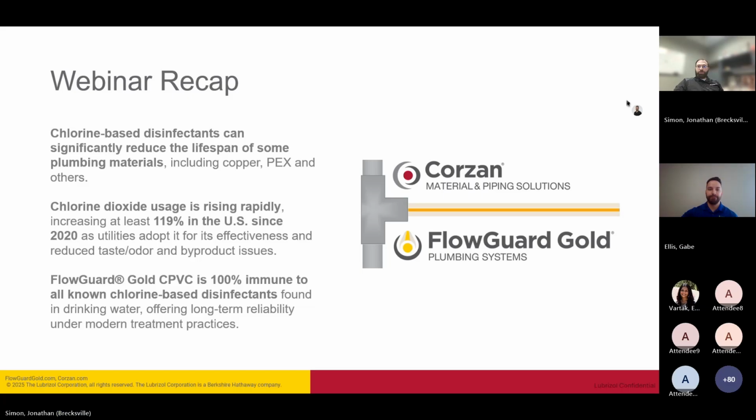Excellent. I'm going to run down a couple quick hitters here on the Q&A. Has there been any update on UV protection for CPVC piping outdoors in direct sunlight? So we don't have any updated guidelines on that. What I'll tell you is that with Corzan Schedule 80 CPVC, that is UV stable, so it's readily installed outdoors without the need for additional protection.